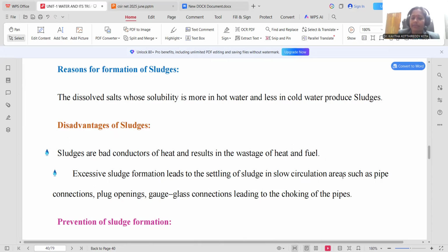Whenever circulation becomes difficult, what happens is that the pressure of the steam circulation increases. If it is not possible, steam will be blocked within the boiler only, so the pressure increases, so that blasting of the boiler may be possible because of these sludges at the cool portions.